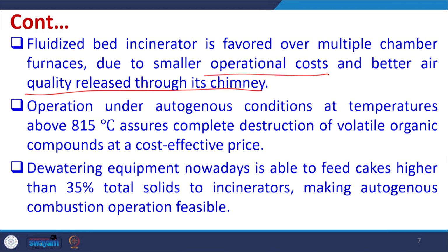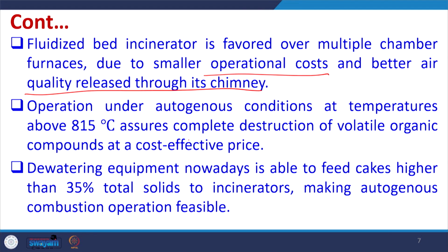So, generally the fluidized bed incinerator will be preferred as compared to the multiple chamber incinerator, because the operation cost is low and the quality of the flue gas coming out is better. The operation under autogenous conditions occurs at temperatures above 815 degrees centigrade, and this assures complete destruction of volatile organic compounds. So, a temperature of more than 800 is good and desirable.